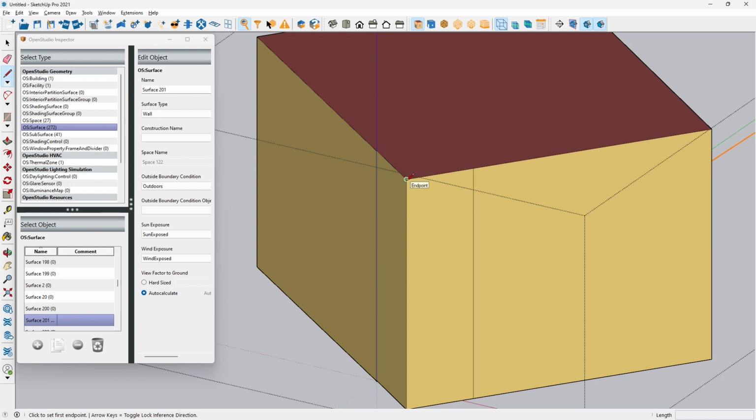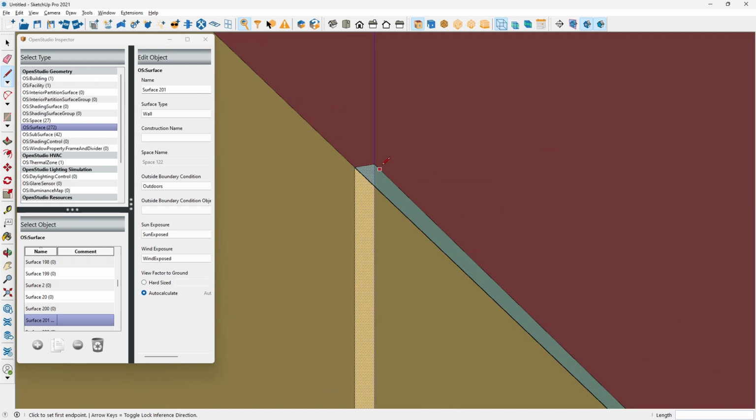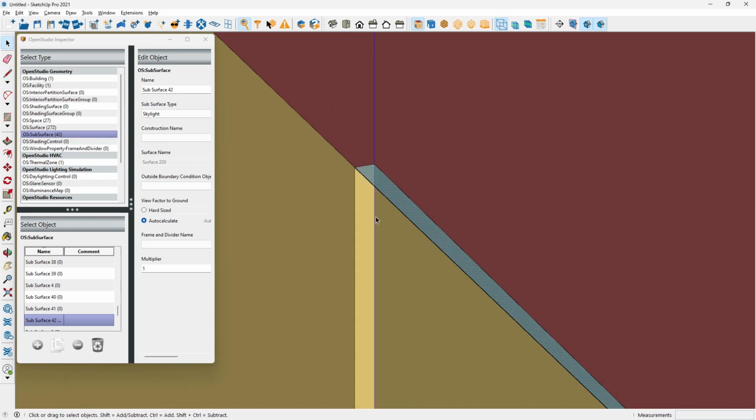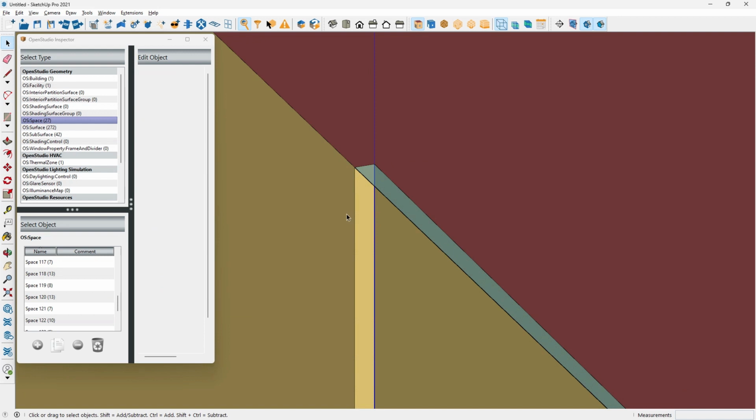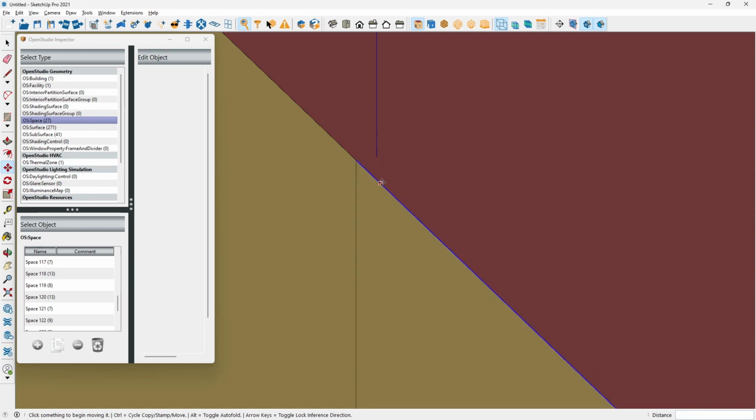But if you did want to resolve that error, if you want to make sure that these are planar, you can draw a line between these two vertices, and you can see that this axis is sort of swept inward. So in order to fix that, you can just simply move this. So we will select this line and click the Move button and move it that way.